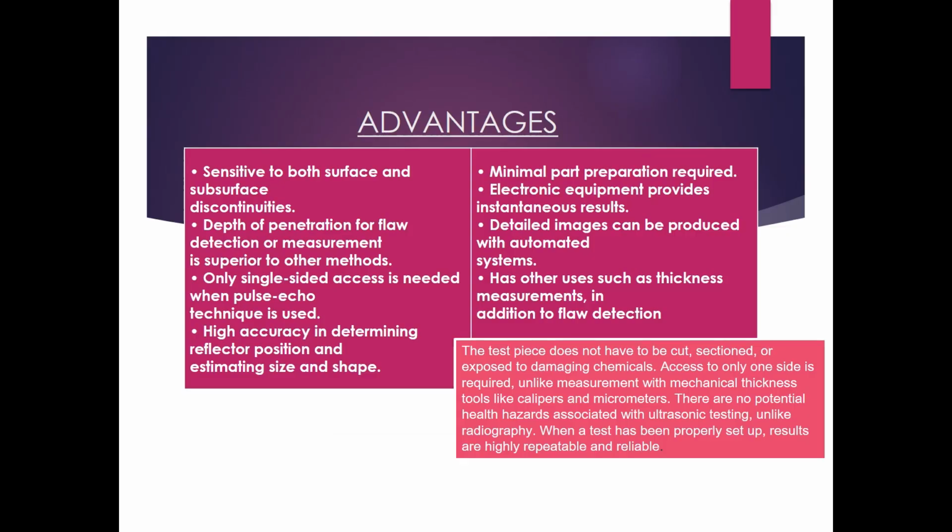There are some advantages of ultrasonic testing. The first one is that ultrasonic testing is sensitive to both surface and subsurface discontinuities. The depth of penetration for flaw detection or measurement is superior to other methods. Only single-side access is needed when the pulse-echo technique is used. There is high accuracy in determining reflector position and estimating size and shape.